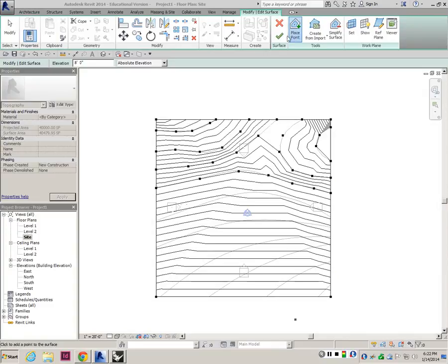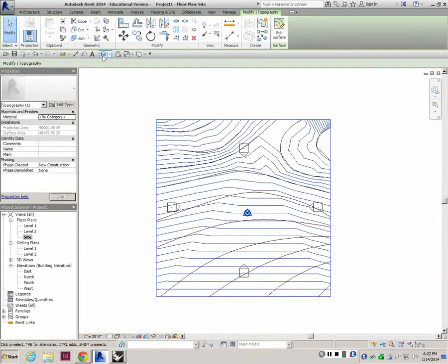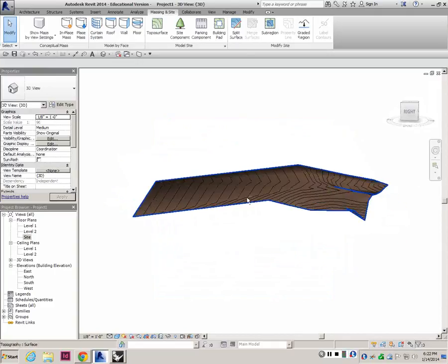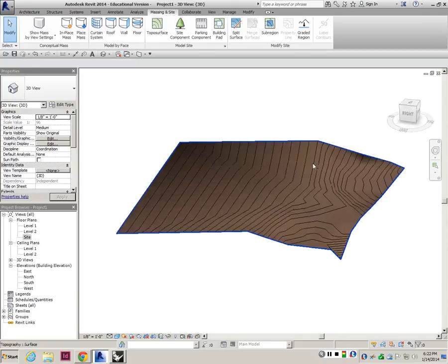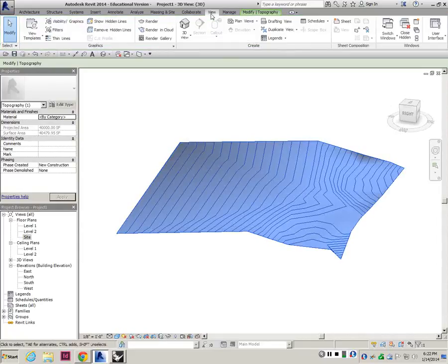So let me exit this first. I'll just click on check. So now I have my landscape, and let's make sure that it's actually being graded. It looks like it is, right? These corners are at 0, but we have started putting in contours. If I want to change the interval of this, I would have to go to, let me see.